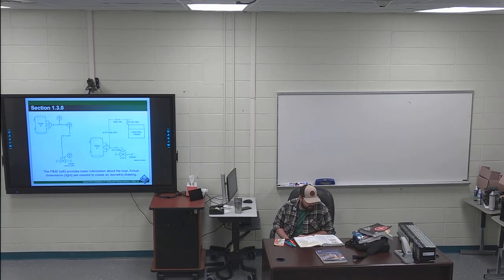Right hand side of page 12, second to last paragraph, first sentence is also highlighted. After determining where the tubing runs must connect, the fitter performs a walk through the locations where the loop is to be placed. That's just to make sure there's nothing obvious that they're missing when engineers are doing drawings and stuff like that. Highly, highly recommend. Go look at the actual stuff, because stuff might have been moved and whatnot, and it's not on the original drawings. Go look.